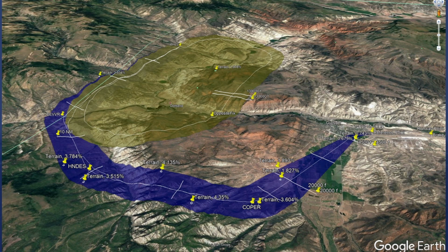So this kind of shows you a little bit about how we design these procedures. We have some fairly sophisticated software developed in-house to aid us in identifying procedures. Now this one was probably an easier design because the SID already shows us a great lateral path. What we're showing here is the blue corridor that you're going to see is based off of the AC 120-91A recommended guideline from the FAA.